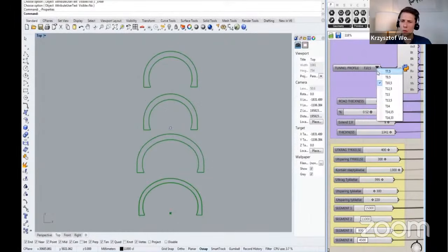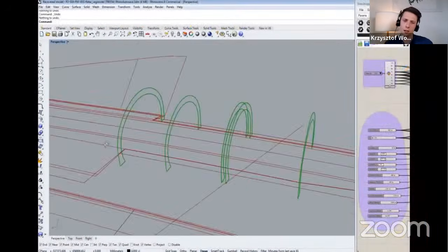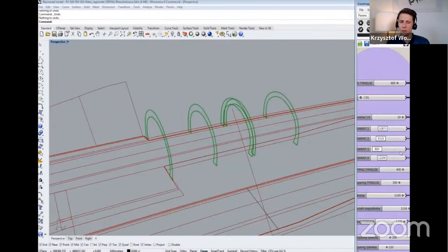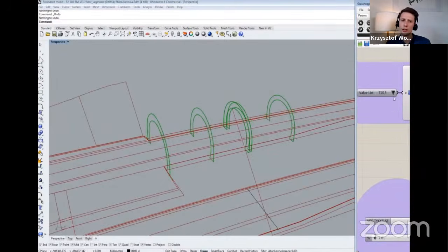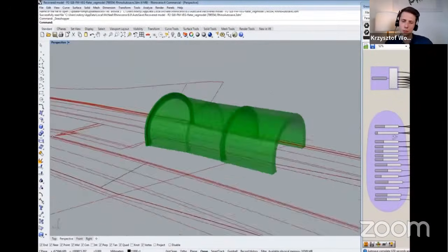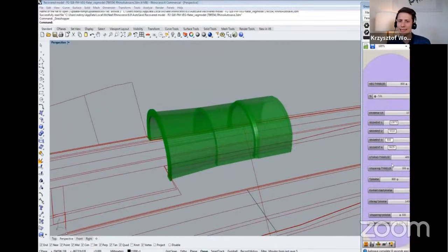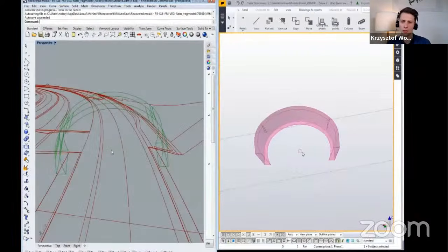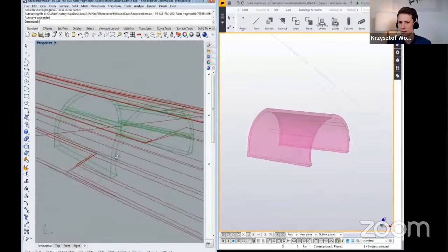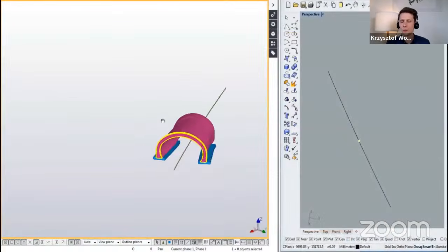In the portals, we have different profiles which are aligned on the line through the road line. As I mentioned, to make it safer you have a wider opening. After alignment, you are connecting all these profiles together to create a really nice B-rep. You can change all the parameters because you don't know where this tunnel will start. Afterwards, you're just sending this 3D model from Rhino to Tekla.